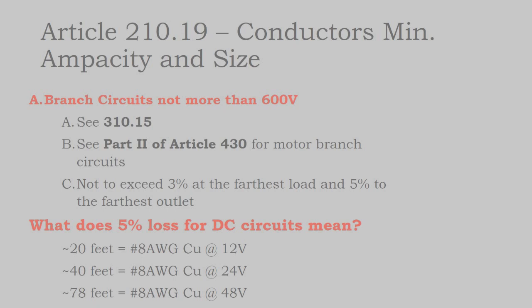Well, in the solar industry, we're usually designing for a 2% voltage drop or less. So we're upsizing our cables for voltage drop, and we would not violate this code. And it's usually cost effective to spend a little bit more money on cable and make it up in efficiency gain.